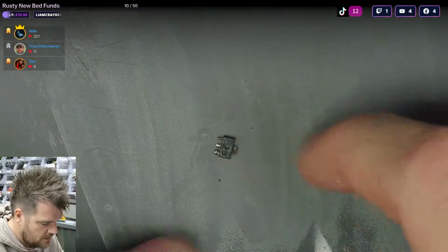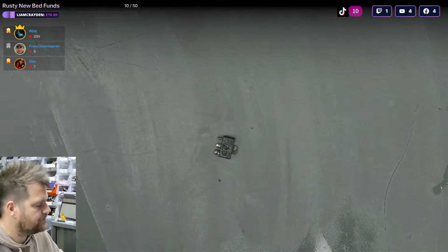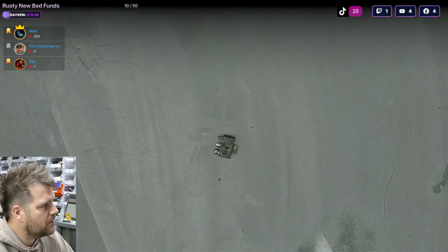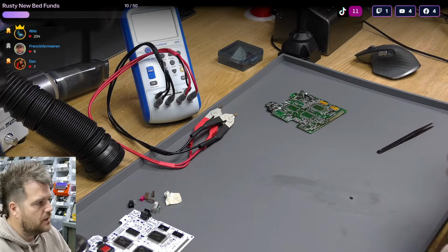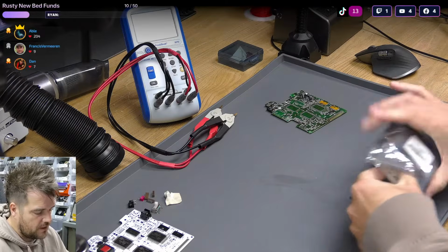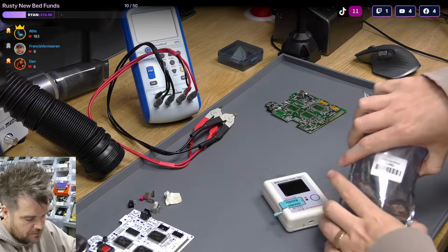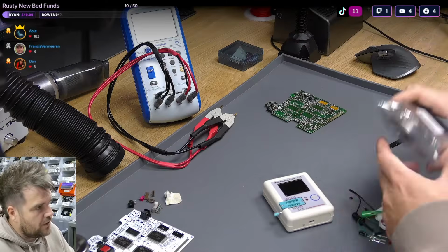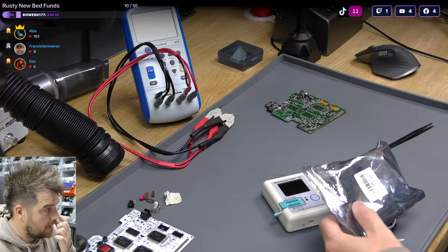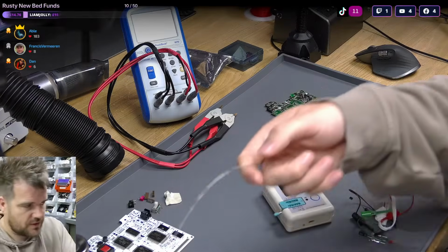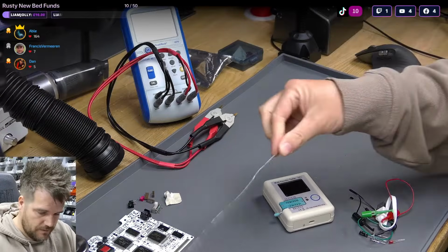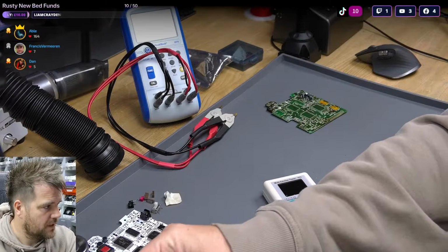Right, so that's there. And what we do with this tester, again, I'd probably recommend if you were doing this on things other than transistors really, you'd probably invest in a decent tester, but the LCR meter's high quality for testing inductors and caps, but for figuring out what transistors we're using, the cheapest component tester is normally good enough.